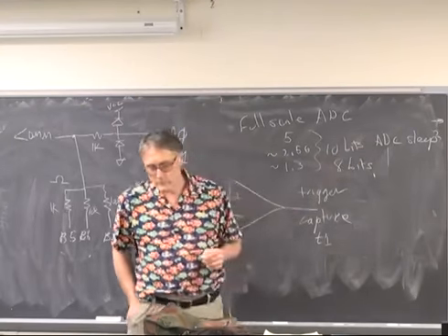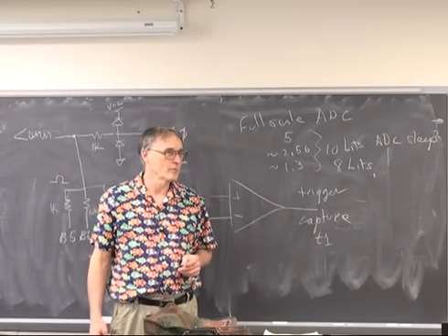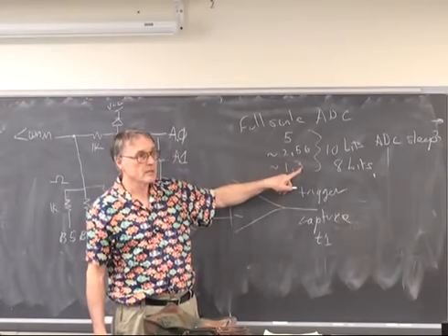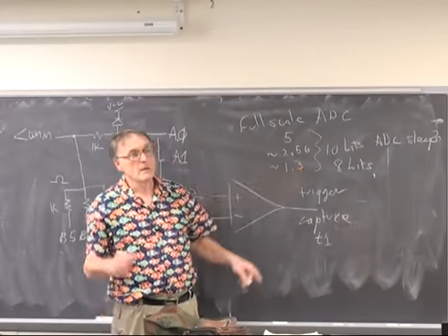I guess the manual way of doing it would be to say apply exactly 2 volts to the input and press go. Now apply exactly 1 volt to the input and press go, and then you could calibrate this scale and this scale. This one you don't need to calibrate,